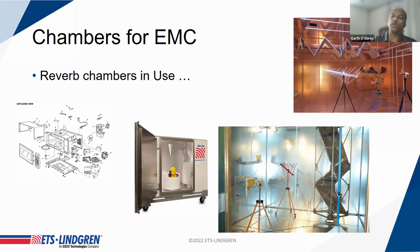I also talked about the 0 to 6 dB that you have for the immunity test environment. That's a 6 dB spread. So we're used to these sort of large numbers when it comes to how accurate is our field or how accurate is what we're measuring. In the communication industry, they're used to much smaller numbers. Fractions of a dB is a big deal. So it is possible to achieve very high levels of accuracy in a reverb environment.